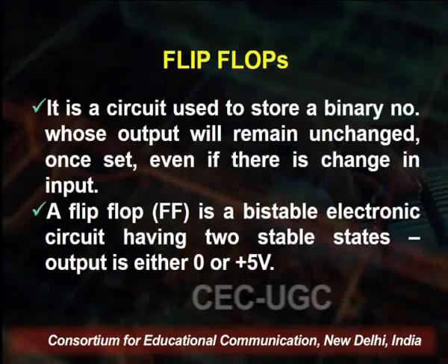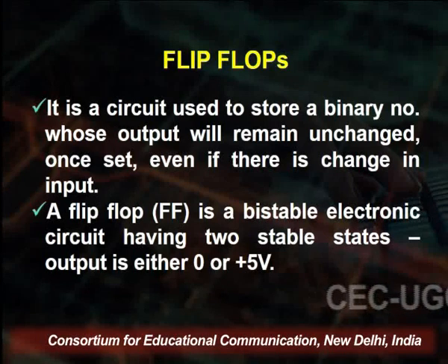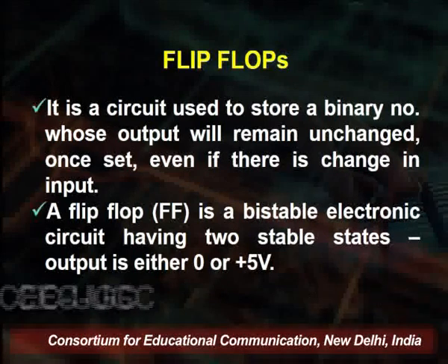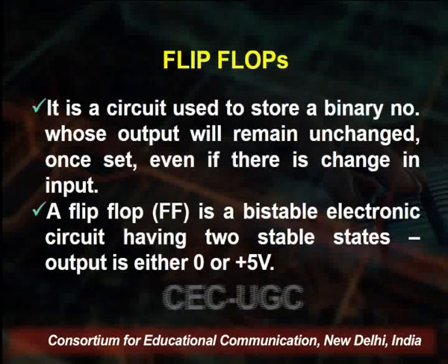We had begun to discuss the basic memory element in digital electronics, which were the flip-flops. Flip-flops, as we saw last time, are a circuit which are used to store a binary number and whose output will remain unchanged once set, even if there is a change in the input.